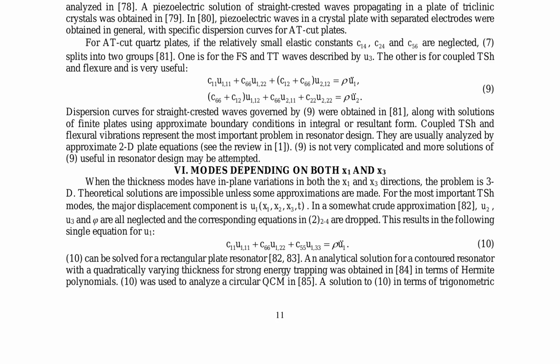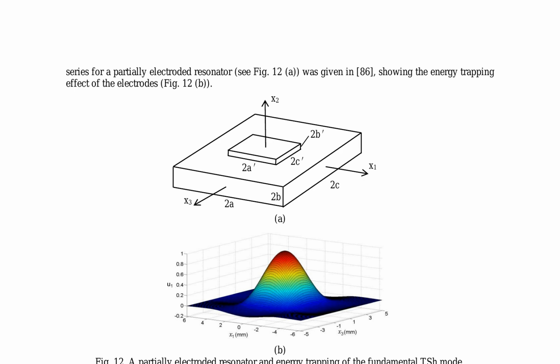The problem of modes depending on both X1 and X3 directions, requiring 3D approximations for solutions, is also addressed. The 3D piezoelectric equations for quartz plates and their various approximations are comprehensively reviewed, along with solutions to different models. These equations provide a fundamental understanding of the behaviors of resonators and acoustic wave sensors, serving as benchmarks for various approximation techniques. The results from piezoelectric analyses are applicable to langasite, a crystal belonging to the same class as quartz but with higher piezoelectric coupling.